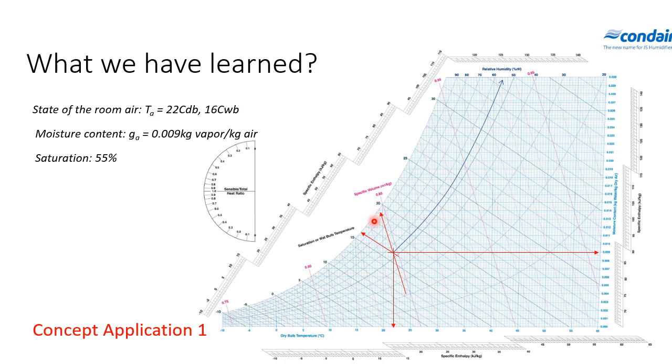So this is very close to 0.85 rather than 0.84, and we assume 0.848 cubic meter per kilogram. This is the specific volume of this room air. It means that 0.848 cubic meter of air will have a weight of 1 kilogram. So it's a reverse density.